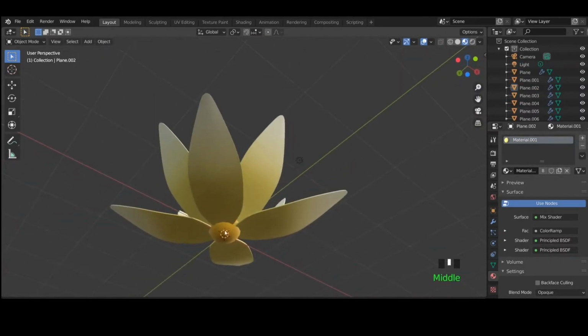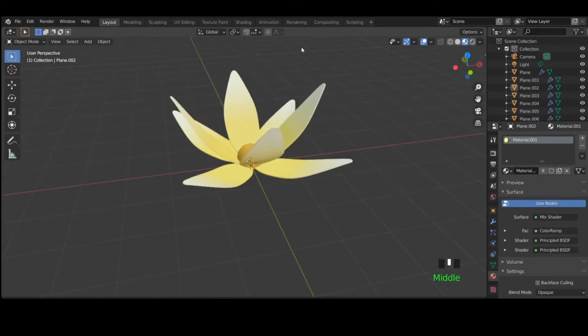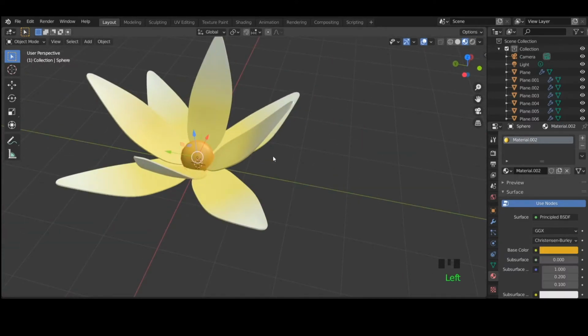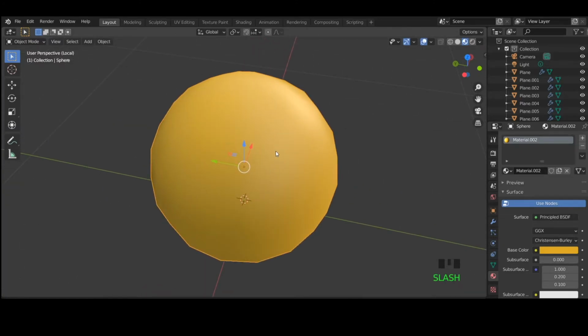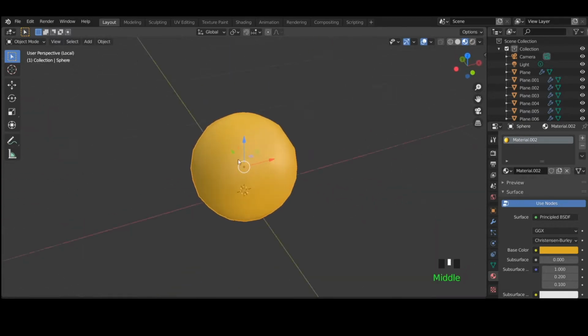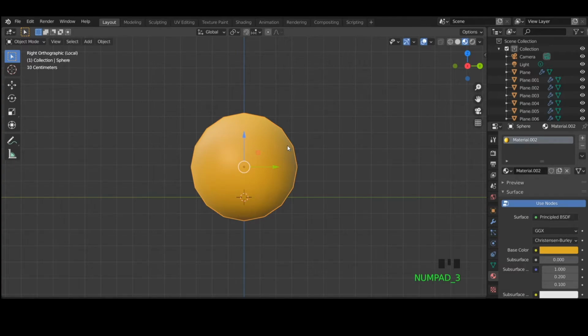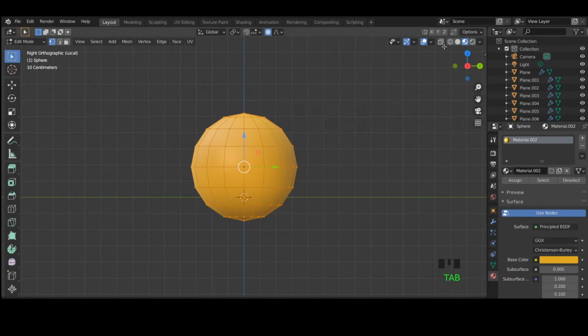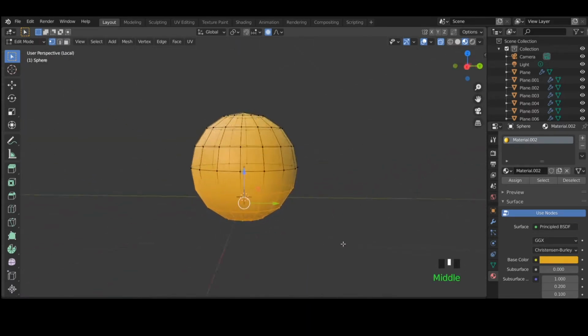Now I just want to color the lower part of this ball green. Select that, press / on your keyboard so that you get into the individual mode, so you see only that ball. Press 3 from your keyboard to get into the side mode, tab into edit mode, enable X-ray mode, and make sure that you have this arrow selected, and select the lower part.